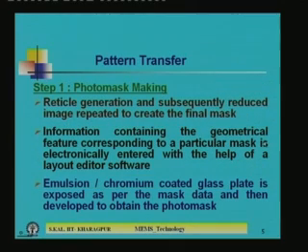So, what are the various steps in this kind of pattern transfer technique? The first step is preparation of the photo mask, that is photo mask making. For that you have to have certain information which contains the geometrical features corresponding to a particular mask, and that geometrical feature is electronically entered with the help of layout editor software. There are various kinds of layout editor software available.